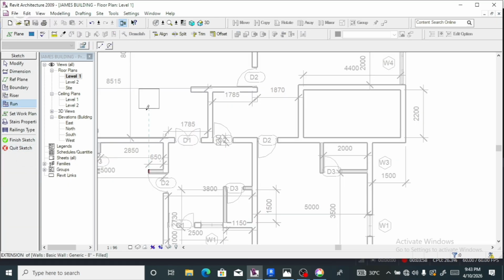You pick the staircase, it's on run, so you have to run it. I want to start from somewhere here and go this way. Click and drag. Escape, Ctrl Z to start afresh. Click and drag to a certain stage. Click again, you drop, go this way, click and drag and drop.